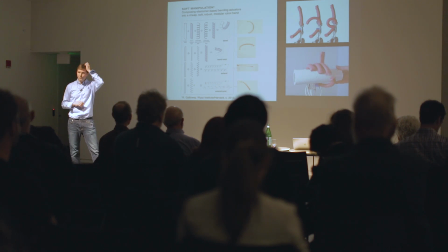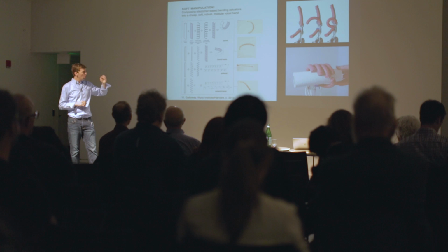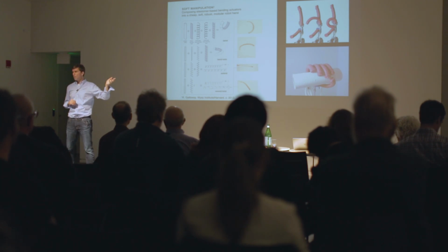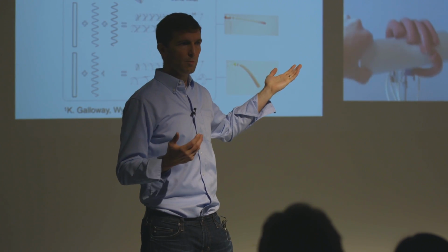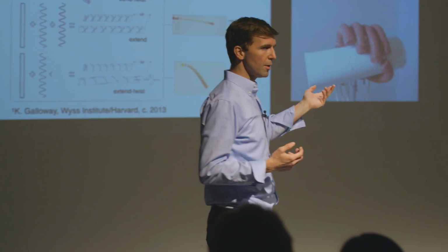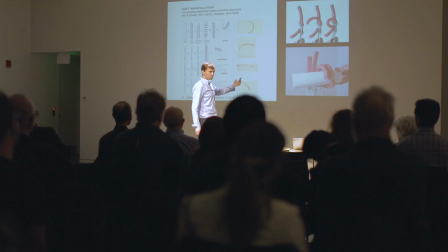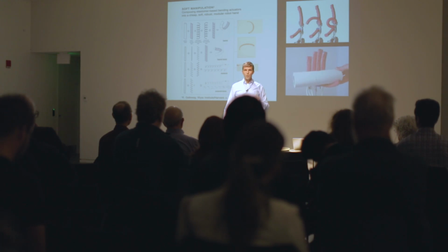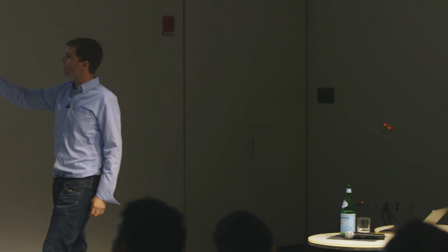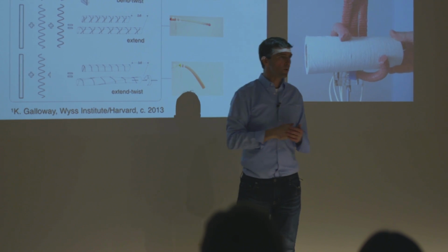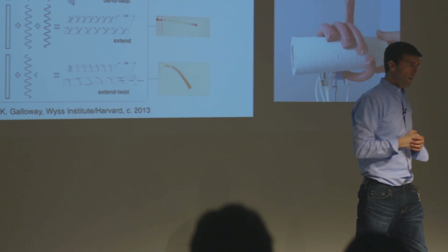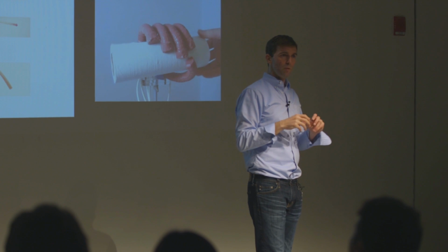We were doing this a few years ago, trying to figure out, if we're going to make robots out of soft materials, how do we make the core components? How do we make sensors and actuators? Very simple things. How do we make a motor equivalent but out of rubber? This is an example where it's just an elastomeric balloon that's being pressurized internally. If you pressurize this thing, it'll change its shape. And one of the tricks that went in here is if I start to reinforce this elastomeric balloon with inextensible fibers or any sort of inextensible material, then I can get extension-bending coupling, extension-twisting coupling.